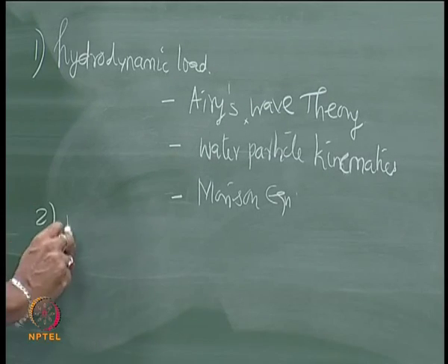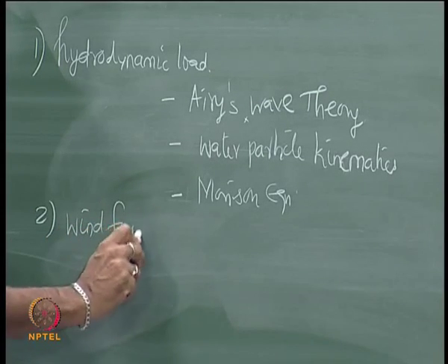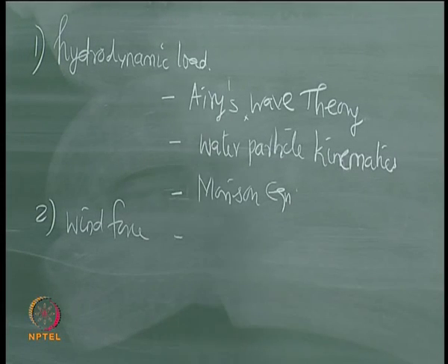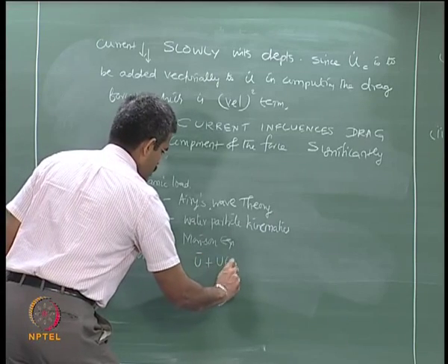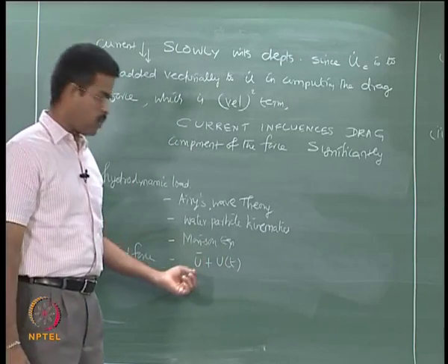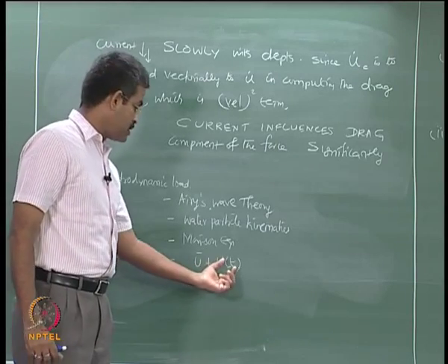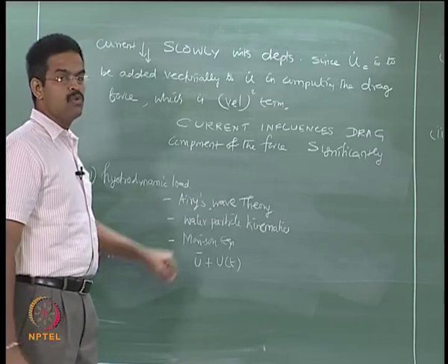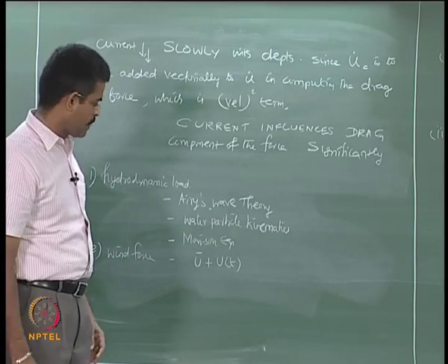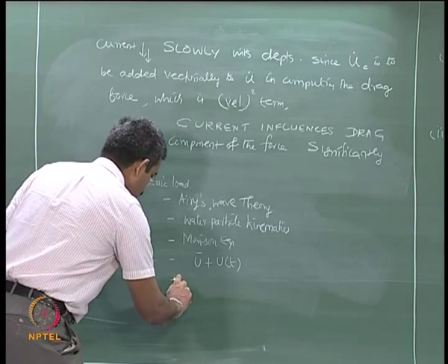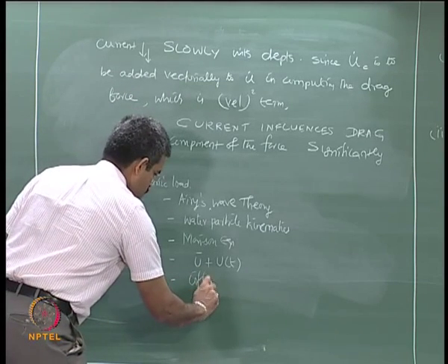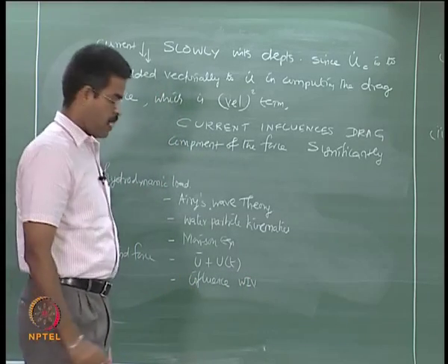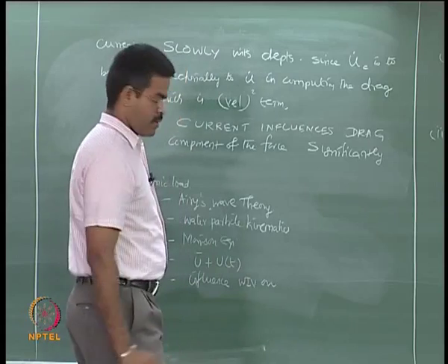We discussed the wind force, that is the aerodynamic loading. Wind force has two components, one is the mean component, the other is the gust component, which is fluctuating. One gives you the static effect, the other gives you the variation with respect to time. So, wind generally causes wind induced vibration on structures. This will significantly influence wind induced vibration on flexible structures.